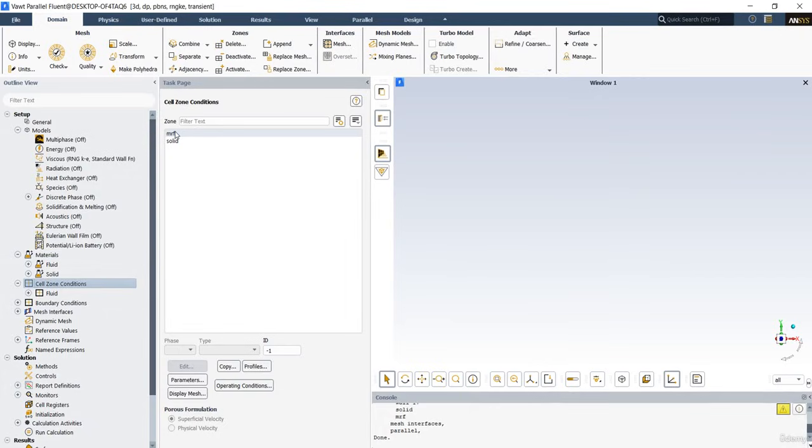In this project, we have two main zones, a stationary zone and a rotational zone. Actually, the turbine rotates in the z direction with an angular velocity equal to 14.17 radian per second, and the airflow in the domain is dominantly affected by turbine rotation. So we use the mesh motion to simulate the rotation.